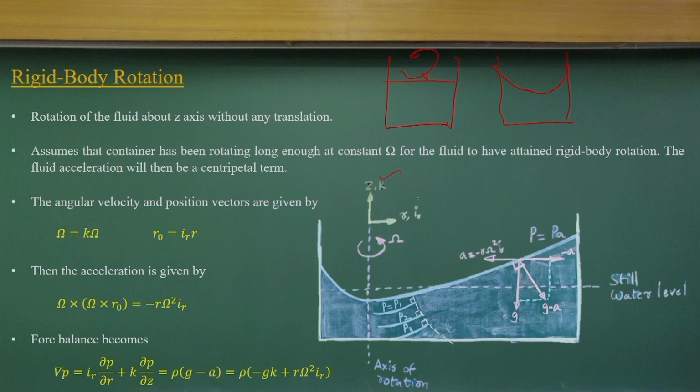But in this case, we are talking in terms of cylindrical coordinate systems. Vectorially we are representing it. This is a quite general problem, so any type of rotation we can solve by considering cylindrical coordinate systems, with k, and the unit vector along the radius, IR, and a uniform rotation. Because of that, the centripetal acceleration will be this part. Okay. Here it is represented as vector notation. Given the position vector and angular velocity, the centripetal acceleration will become, as you know, minus rho omega square IR.